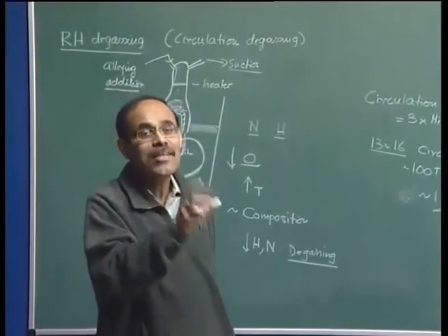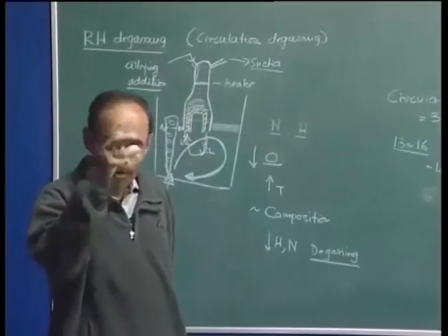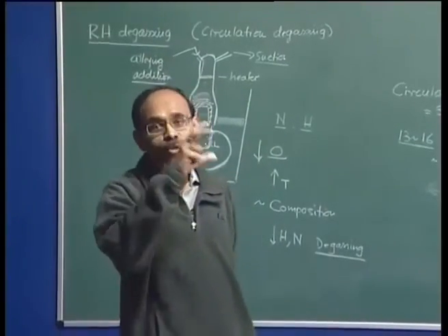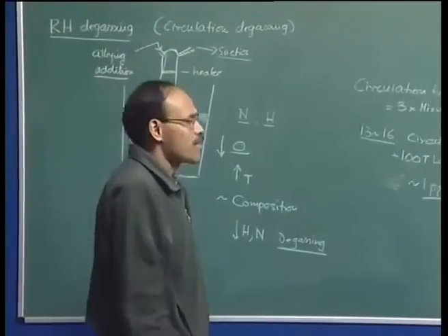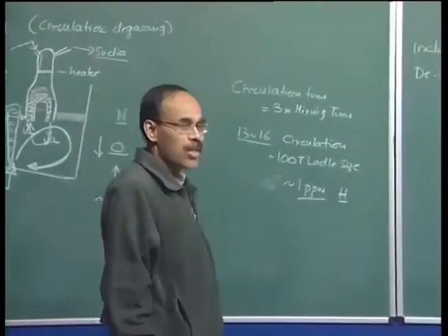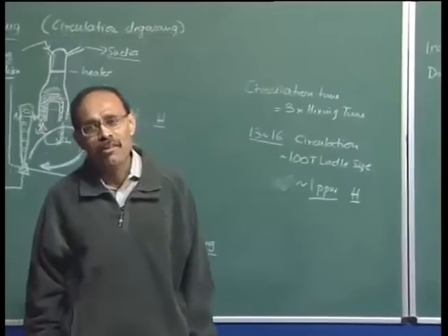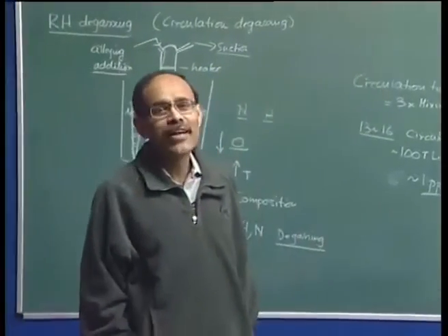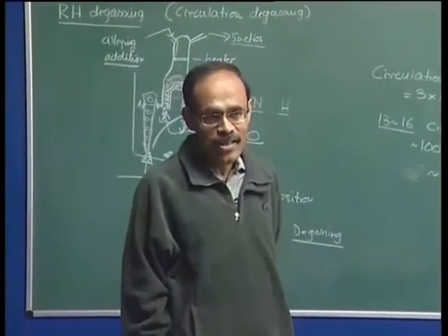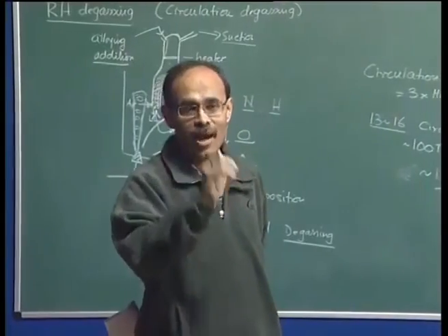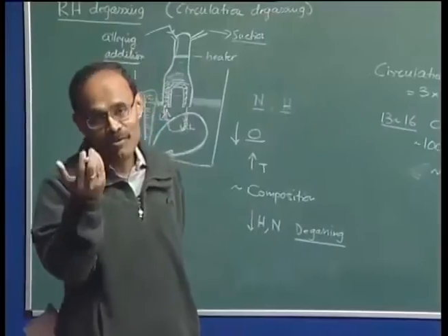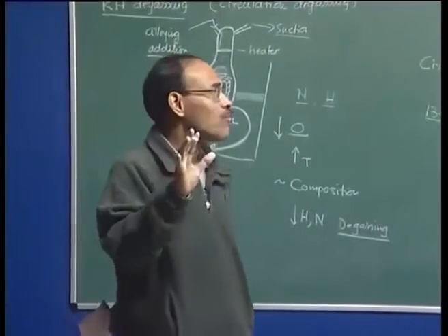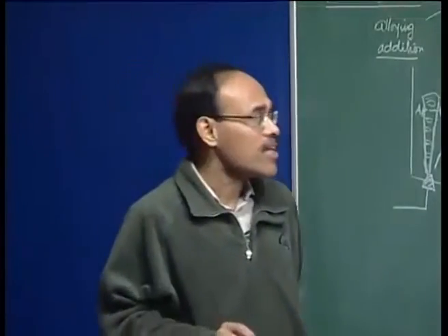because more silica means more temperature, more silica means more slag volume, more silica means more lime. So therefore, if we cannot eliminate a lot of sulfur in blast furnaces, sulfur removal cannot be achieved to a significant extent in basic oxygen steel making furnace, because the conditions thermodynamically are not favorable there. We have a high oxygen potential, and we all know that sulfur removal is not facilitated under oxidizing environment.